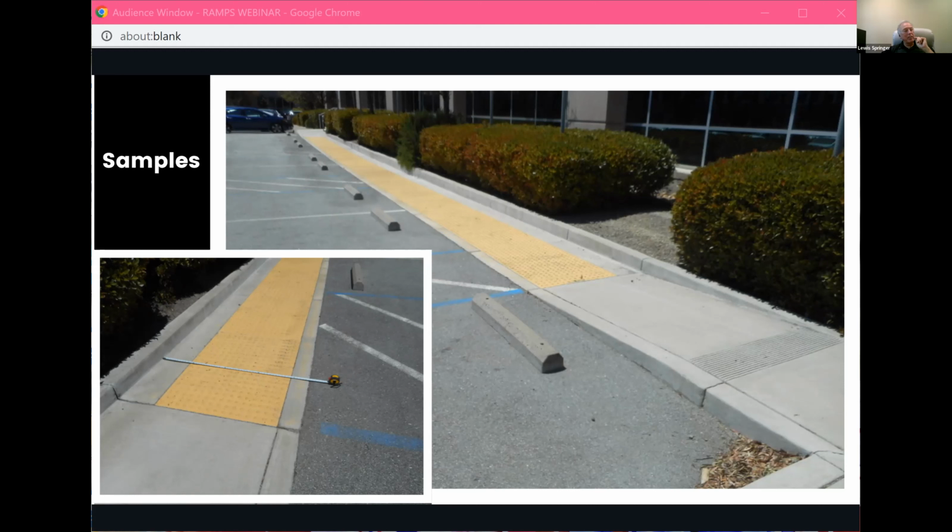Like I said, there's nothing in the code that says anything different than that, even though the diagrams show that the curb ramps are the same width as the ramp. That's not necessarily the case. Literally, on that double loaded one where there's 36 and 36 and a 36-inch concrete space in the middle, if you had a 48-inch wide curb ramp going off that space in the middle, you don't have to have that concrete ramp the whole way. That makes sense.